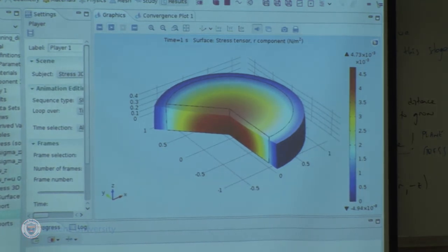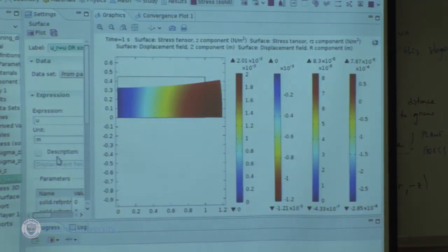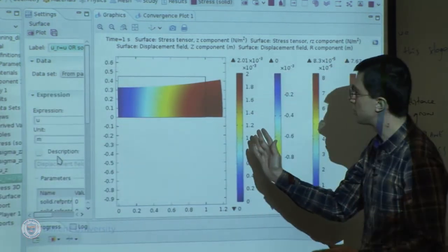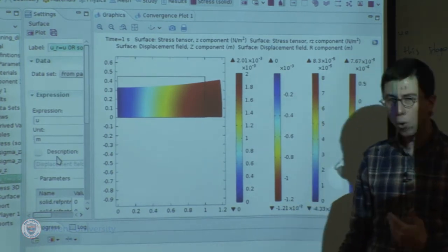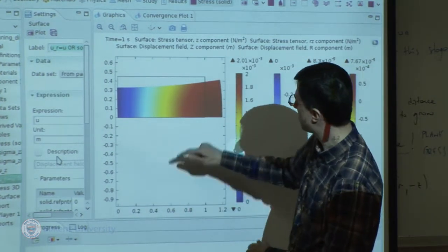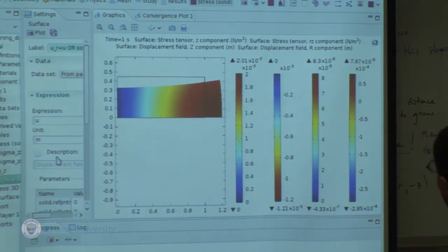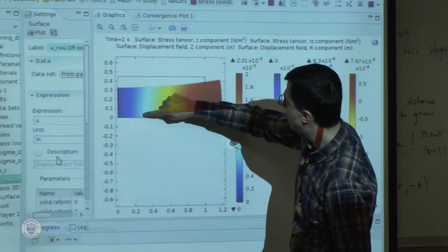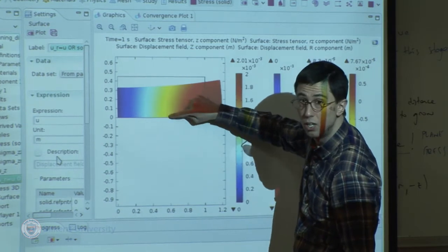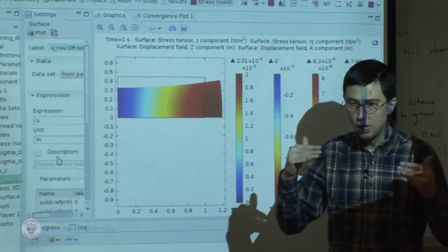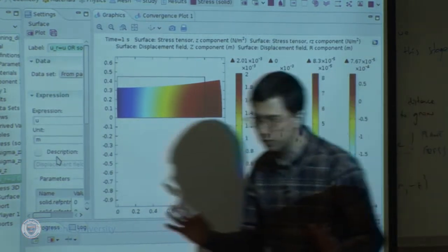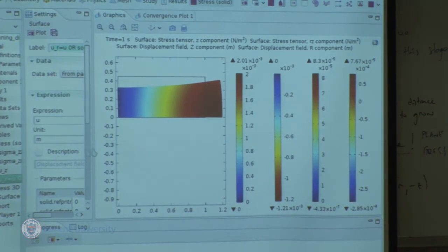And therefore, if you look at, first of all, this is the radial displacement. If it were only r dependence, maybe it's not very easy to see. Let me look from far. Okay, it's more clear from far. There are these colors that curve like this, which means that the radial displacement depends on the z direction. So z dependence of ur cannot be omitted. And as I already noted, this is a thick disk. Perhaps when it's thin, it might be omitted.